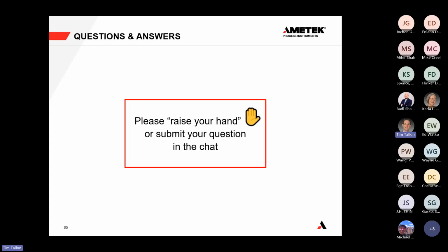That's been used tried and true. Its predecessor, the WG-HP2C, was used tried and true in very heavy particulate applications in cement and lime and pulp and paper and industrial waste. And we continue to recommend that particular product for high particulate applications. We have other options too if there's a light amount of particulate, but if it's very high particulate and very high temperature, I'd be the first to recommend the WG5HP for that application. Okay, great questions.